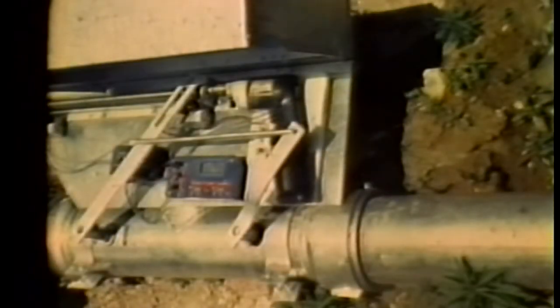The valves may be operated manually, or they may be remotely controlled from a centrally located control station or a substation. Automatic systems may be designed to start operating at certain time intervals. This type of system uses electric timers to start and stop each irrigation cycle. Automatic systems may also be activated by moisture sensing elements that are placed in the soil. The moisture sensing instruments start the system when water is needed and allow the system to operate until the entire field is irrigated.